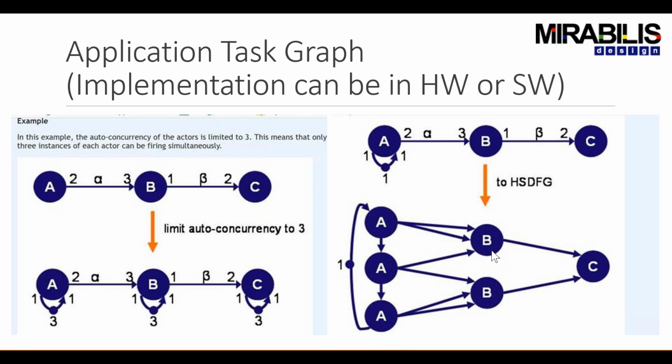It may happen sometime in the future as a result of, say, too many refreshes on my memory controller, on my DRAM, that might cause some of the resource requests for memory to get delayed, and as a result the processing gets delayed, and the credit going back to the earlier stages also gets delayed, and then you have buffering that slows down your entire system.